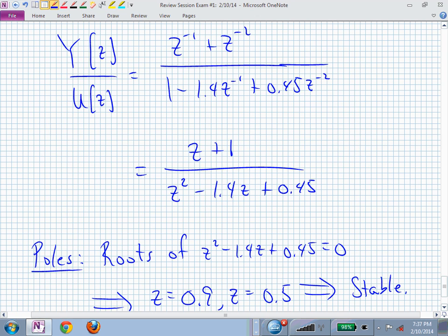It could be the Laplace transform of a unit step, or it could be an integrator as an operator. That's sort of what we're doing here. We have a transform, capital G of z, that's representing a system. We want that system to be stable, which means if we hit it with bounded inputs, it better produce bounded outputs. That requires the poles of that system to be inside the unit disk. We didn't have to worry about a region of convergence.